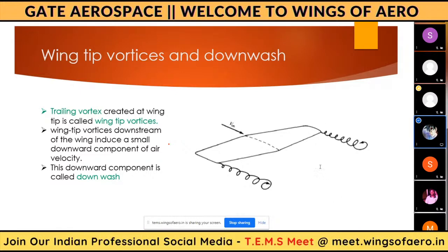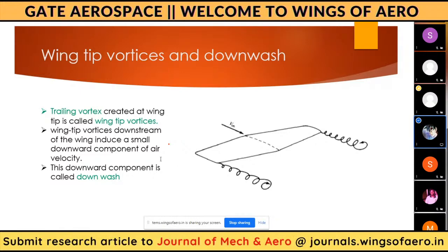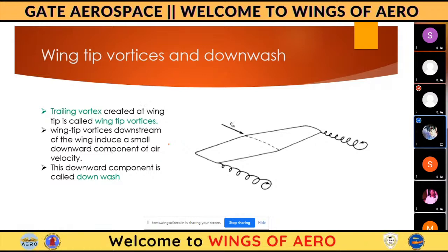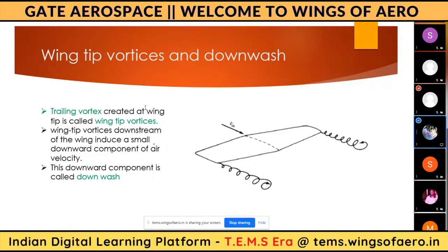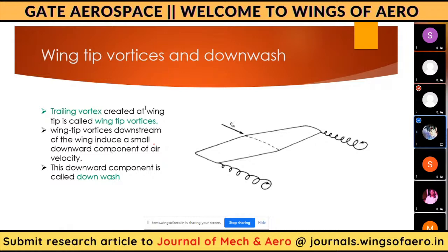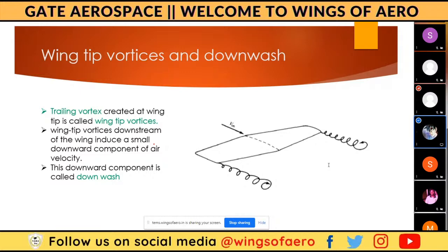Have you done any computational analysis in ANSYS? Excuse me, can you please explain what is called the downward component? I have had this doubt for a long time, sir. Downwash, what is the exact meaning of it? Yes, the last session also I explained it. Once again, downwash means, when the flow is over the aerofoil, at some point, the air from the bottom surface tries to move upward, and it will form like this. I will just show you.